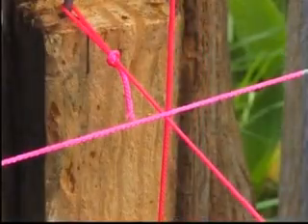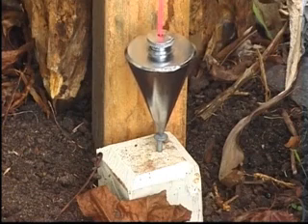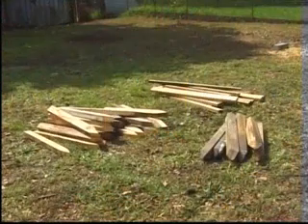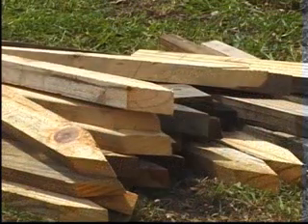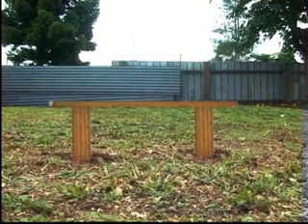An adequate supply of pegs, string lines and profile materials should be on hand. Profiles are pairs of pegs driven into the ground with horizontal cross members fastened to them. The cross member or ledger allows sideways adjustment of string lines during setting out. Where the ledger is fixed to the tops of the pegs, a profile is called a saddle.